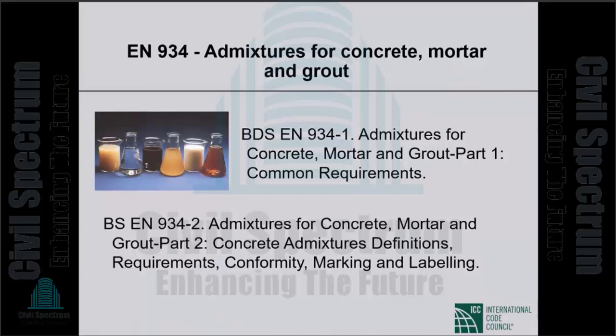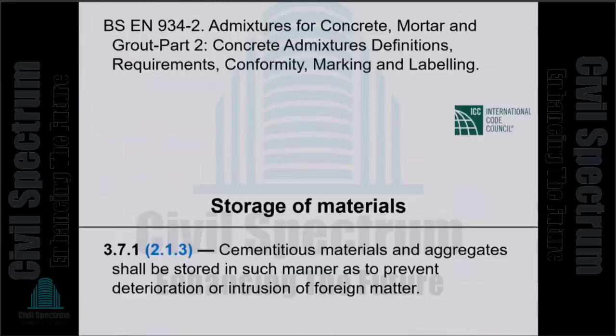BNBC cites BDS EN 934-1. Those are admixtures for concrete, mortar, and grout. Part 1 is common requirements. 934-2, admixtures for concrete, mortar, and grout. Part 2 talks about concrete admixture definitions, requirements, conformity, marking, and labeling.